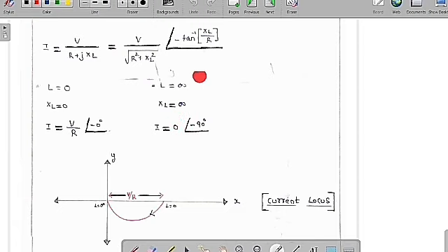You can see clearly as L increases, XL also increases. As XL increases, we can say that theta is also going to increase. So we can say it is going to increase from minus 0 degree, minus 1 degree, minus 2 degree up to minus 90 degree. So we are going to get the graph in this format, from 0 degree, minus 0 degree, minus 1, minus 2, minus 3 up to minus 90 degree, with a decreasing amount of amplitude. Therefore we are going to get a semicircle.